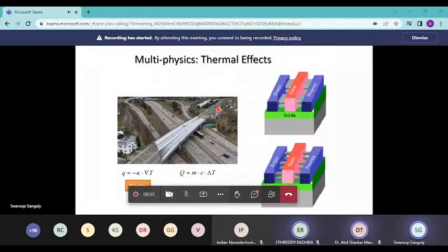And if you have driven a car in very cold places, you often see that before you come up to an overpass, you will see a sign which says to watch out for freezing on the bridge because of this effect. Now, why does this happen? Again, I would have liked to ask you face to face, but let me give you the answer. It happens because this part is not connected very efficiently to the heat sink, which is the earth.